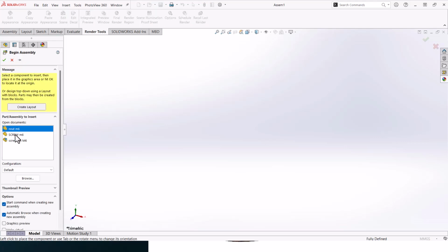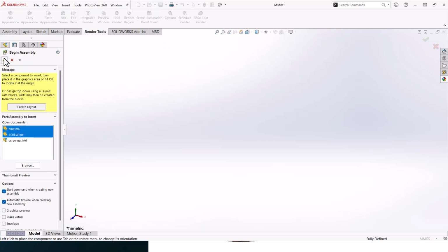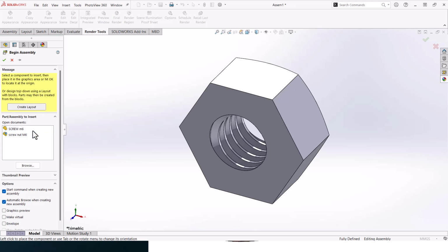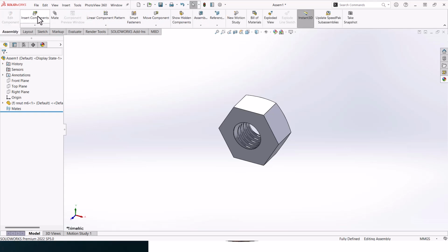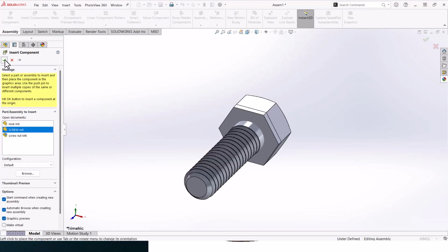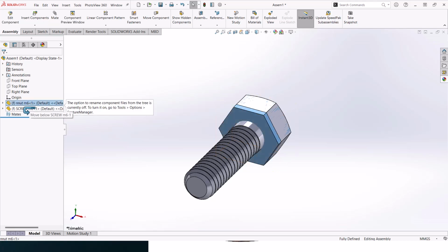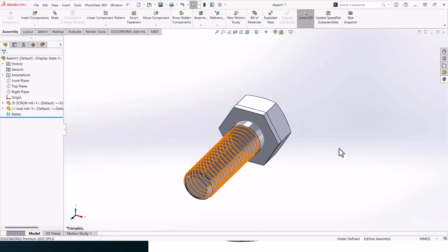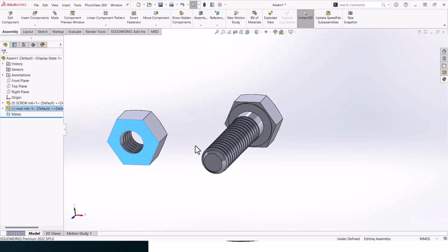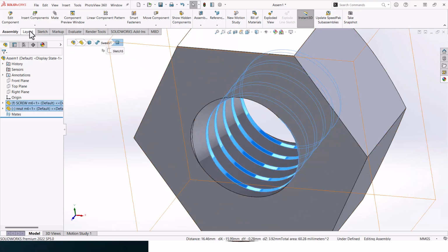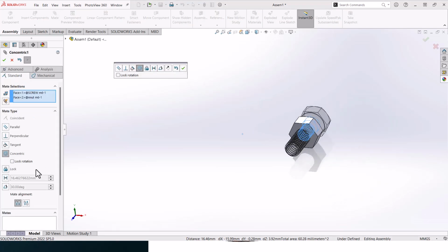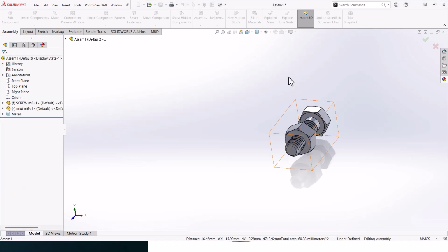To create the assembly, you should go ahead and bring in your screw and nuts as well. Screw. Assembly. Insert screw. Good. Now let's float the nut. Alright, let's make it. Let's go to constraint to mate. Let's make it concentric. Good.